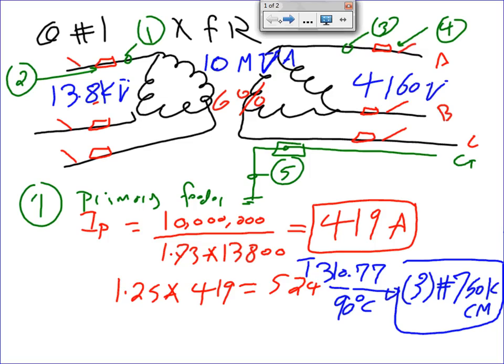Expulsion proof, rated. The reason why I brought this one with me, guys, it's rated for this guy. If you read it, it's rated for 15.5 kV. Would that be cool if it's rated 15.5 kV? Would it be good at 13.8? No problem. And the amps on it is 65 amps. It doesn't work on this. We need a bigger amp than that. The interrupting rating for it is 50 kiloamp. 50,000 amps can interrupt 50,000 amps at 15.5 kV. A huge amount of energy out of this.